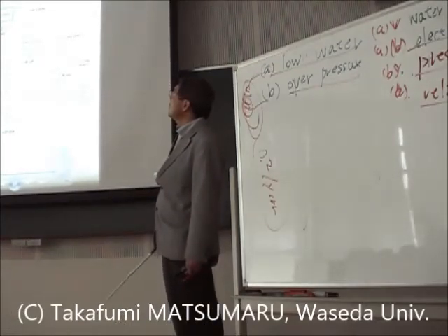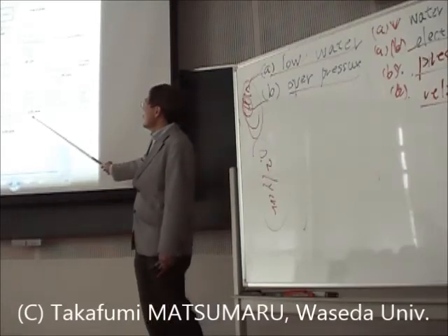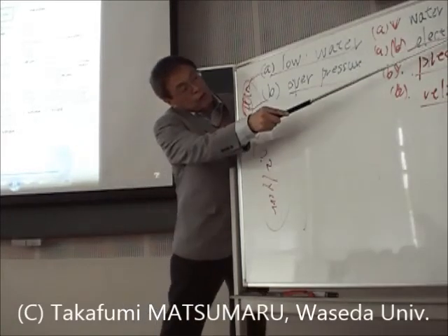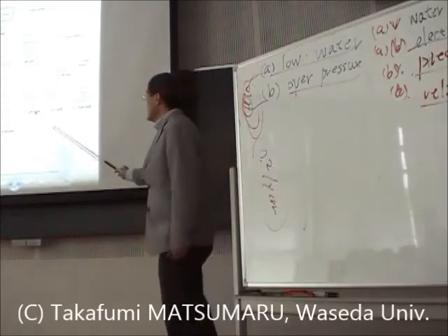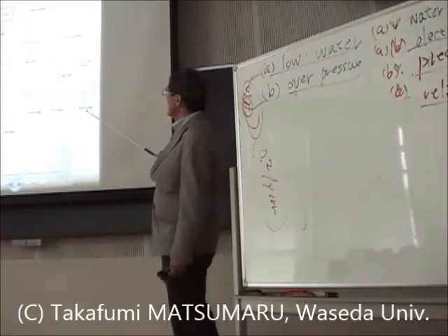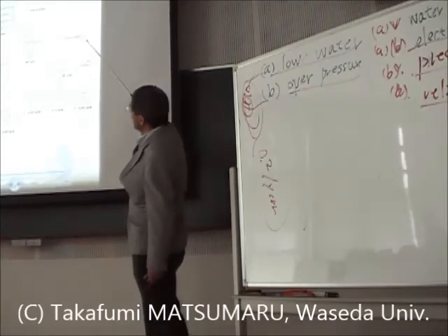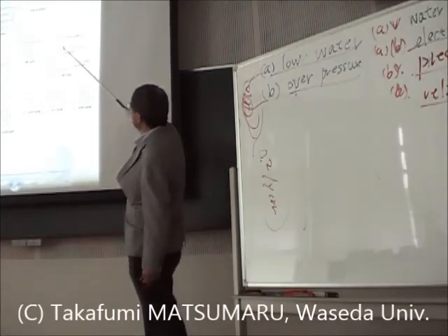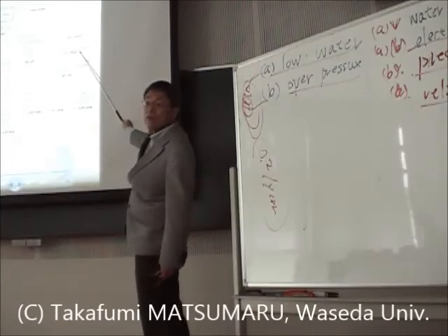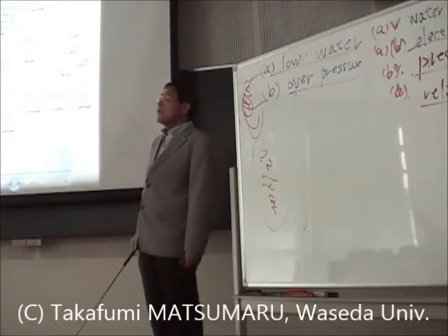And for the electrical fault, 0.05 per year. For the pressure switch, 0.1 per year. And again, for the relief valve, 0.05 per year. And again, because this is an OR gate, we add the frequency. So we get the frequency of the overpressure, it is 0.1 plus 0.05 plus 0.05, giving us a frequency of 0.2 per year.